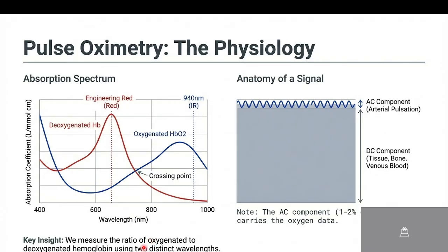You can see here in the absorption spectrum that the deoxygenated hemoglobin, which contains porphyrin and iron, has absorption in the red region, around 650 something. But when it's oxygenated, the absorption region shifts to approximately 940. Because of that, it can be useful to understand how much oxygenated concentration there is in hemoglobin.